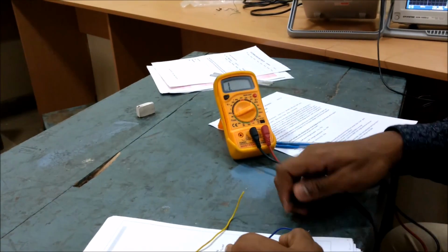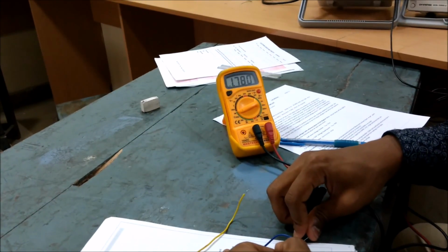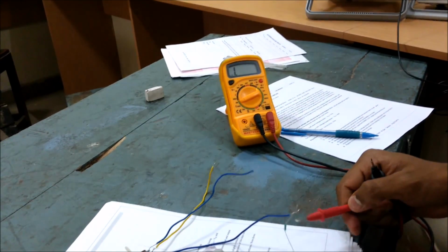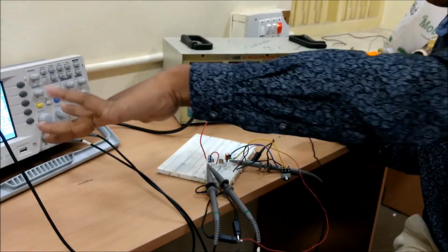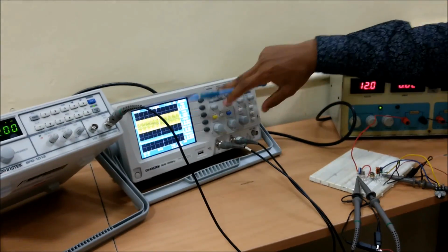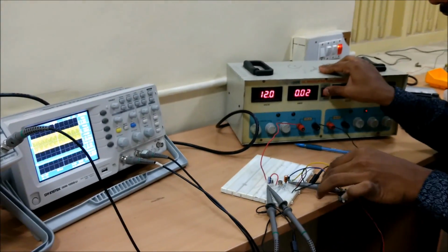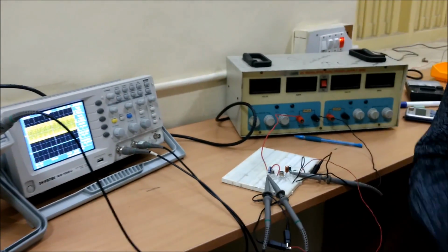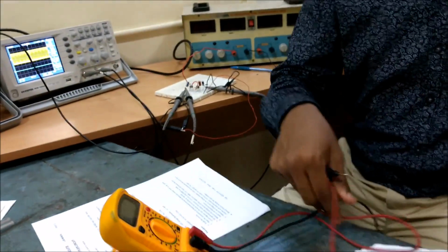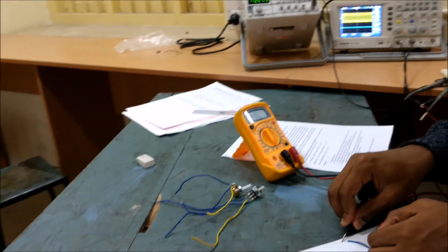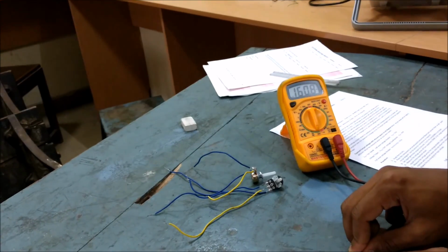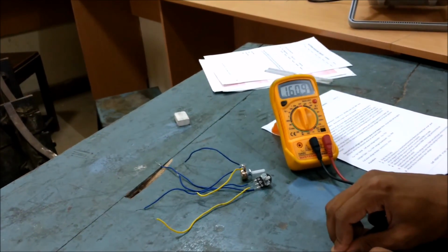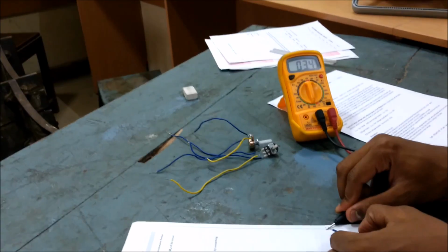So we will see the output impedance with the bootstrap. Connected the output pot, 1 kilo ohm, and we can see that the output is exactly reduced to half. Okay, pick up the power supply and calculate the output resistance. You can see that it's around 160 ohm. Okay, that's acceptable. That's less than 470 ohm. It's a much better output, lower impedance.